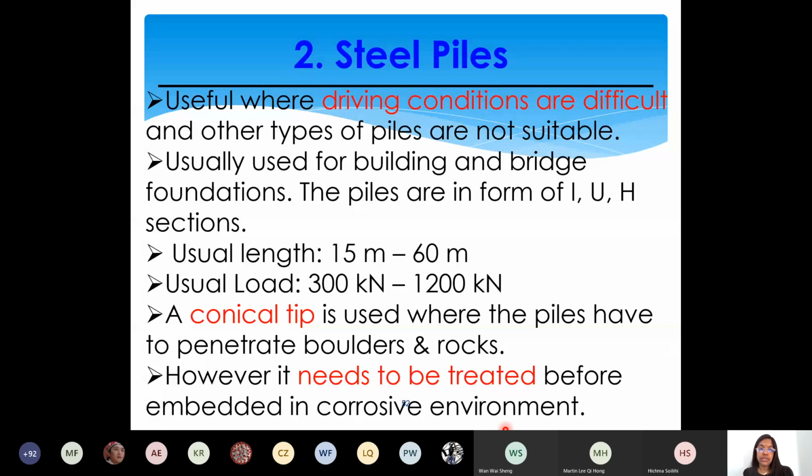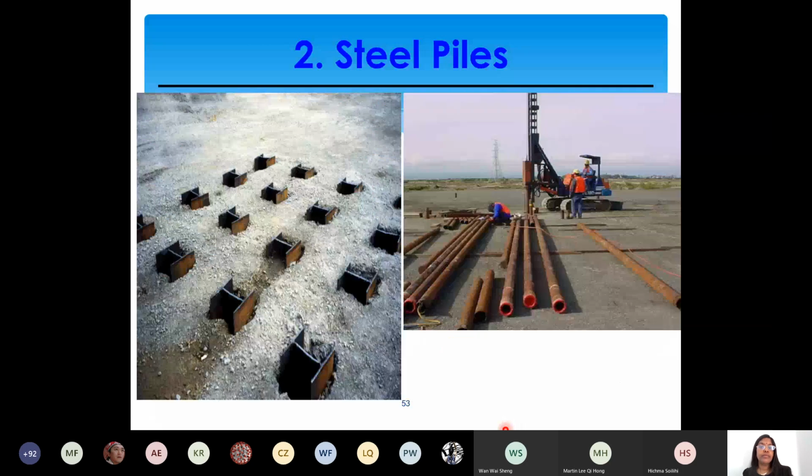The major problem of using steel is corrosion. To avoid corrosion, it should be treated. Apply corrosion resistant material or any water impermeable material to keep it away from corrosion, because it's the base material, right? The bottommost portion of the building on which all the loads are transferred all the time. So avoid corrosion, which will lead to failure of the pile.